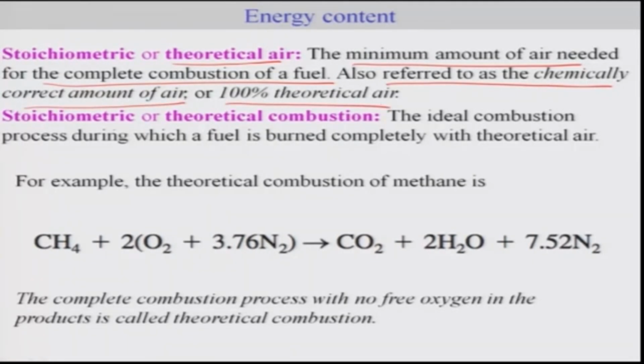So the stoichiometric or theoretical combustion is the ideal combustion process during which a fuel is burned completely with the theoretical air. This is an example of combustion of methane. One mole of methane will take 2 moles of oxygen, leading to complete combustion to CO2, H2O water, and whatever remains, the inert, will come out as it is.